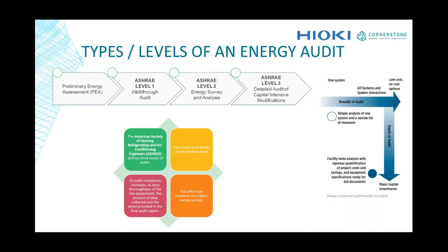Now, let's say you really want to move into retrofitting, and your goal is to retrofit a building. Then what is usually recommended is an ASHRAE level 3 audit, which looks at whatever has been done so far up to level 2, but again, readings are taken for a longer period of time. The idea is that as we move through the different levels, the accuracy of the savings as well as the overall proposal for the building increases.